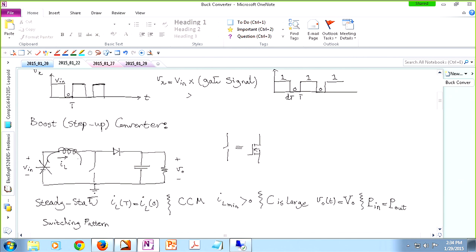So if you want to turn something on or off in the lab, I would say, remember, all of the power supplies that we have, they are not like a battery. There's a knob basically. You can start from very low voltages, gradually go up, and when you want to turn it off, do not just push it off. Gradually go down. So you gradually increase your input voltage to get to, for instance, 48, and then when you are done, gradually reduce it down to 0 and then turn it off. So that is the very first protection measure you can take.